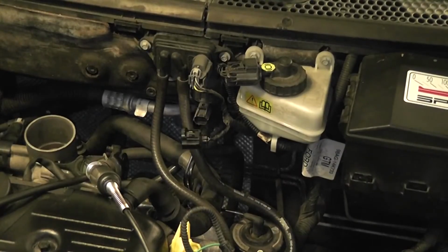Okay, there's a couple different ways to check this DPFE sensor, and of course we're limited in some of the tests because the solenoid's bad. One of the ways we could do it is energize the solenoid, engine idling, look for a rough idle, look for the DPFE voltage to change. I've shown you that in other videos.